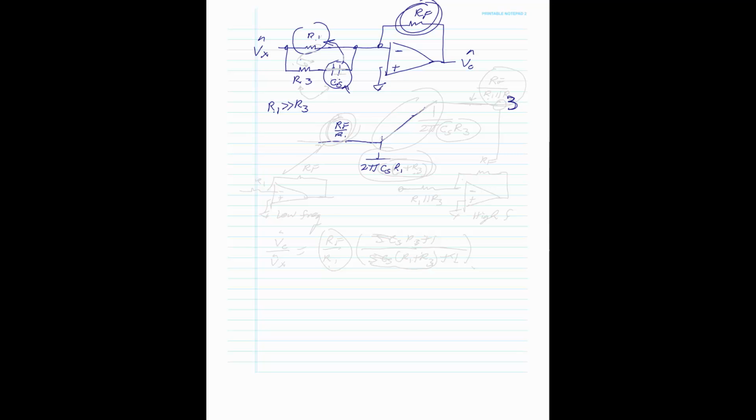Now when it goes up here, it's of course actually this plus this in reality, but again, if R1 is much greater than R3, it's approximately R1. But for all intents and purposes, to be a perfect equation, we have this, because when you look at this, it's these in series. Now, how does it stop going up? It keeps going up until when? Until this capacitive reactance is equal to R3.